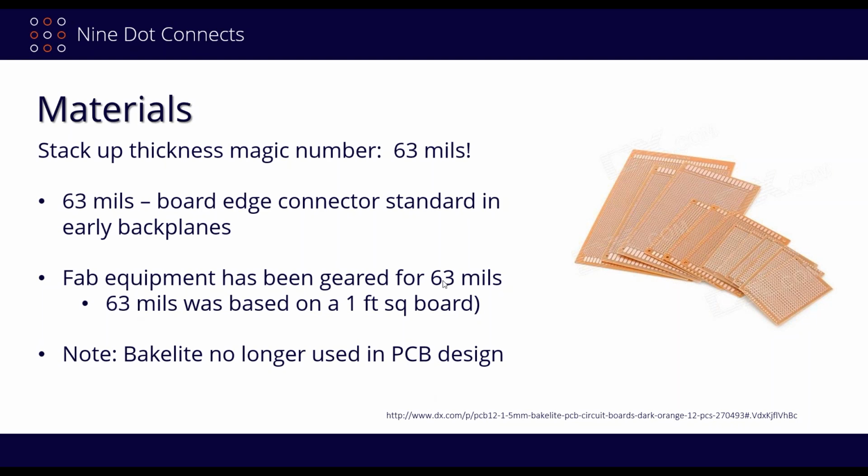As a side note, Bakelite is no longer used in the PCB industry. It's been long since phased out. You don't generally see Bakelite in products anymore. As I mentioned earlier, there are a lot better products and plastics that have substituted for Bakelite. The biggest problem with Bakelite is that a good component of its material makeup is formaldehyde. And as you probably know, formaldehyde is currently considered a possible known carcinogen. So no company really wants to play with that stuff at this point.